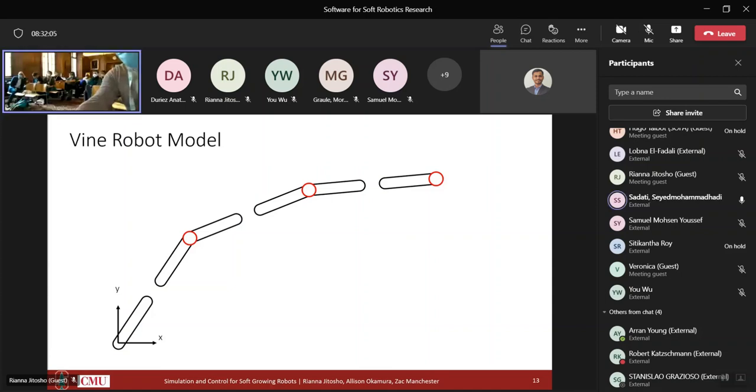So in our implementation, the contact points coincide with the pin joints, but this choice is arbitrary and a number of options are completely valid. So we could do something like add a higher density of contact points or shift their location to the centers of the link, and any of these would be reasonable. The main requirement is that the spacing between contact points remains relatively small. And this is relative to objects in the environment.